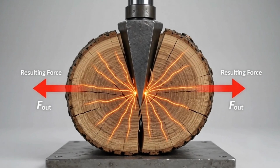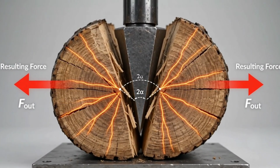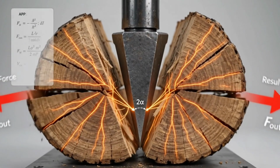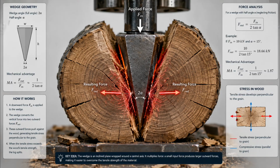When a force is applied to the broad end, the wedge redirects that force outward through its sloping surfaces. The mechanical advantage is approximately MA equals length of wedge divided by width of wedge. A longer and sharper wedge produces a greater force amplification.